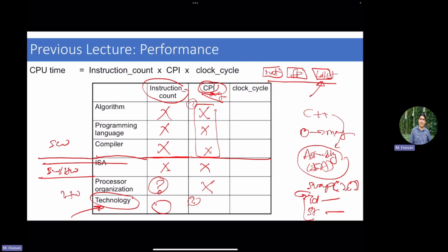clock period, right? And this, I guess, is also something you can more or less make a conclusion about from 3DQ, right? How you design your RTL simply determines how fast you can run, which is what we call the critical path Fmax, right? This is what defines your clock speed, right? So hardware design, RTL, computer organization clearly defines your running frequency. Technology,